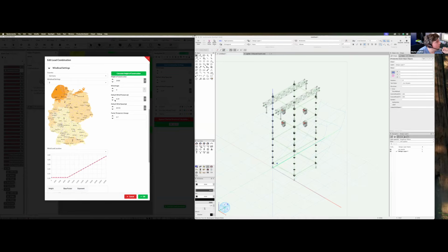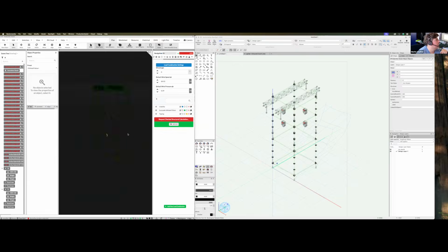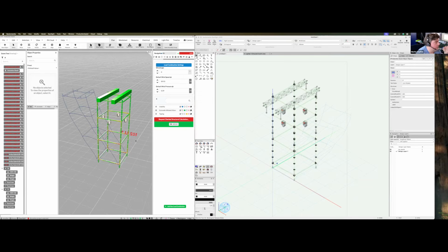You see the 0.39 is also quite something. If you go to the next, wind zone 3, this increases a little bit, to the highest force, the 0.56, which is also the default value in Production Assist, so that you don't run into any problems in here. So we will change it back to wind load zone 2 and press OK. And you see the calculation is automatically updated, and there's a slight overload in here, so we need to do something about it.